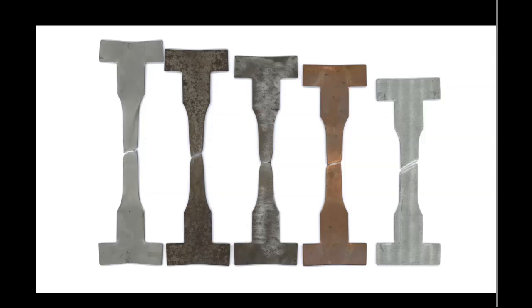So modulus of resilience, which statement describes it? A, the total energy absorbed by a material up to fracture. No, that's wrong, because at fracture both elastic and plastic deformation have already been at play. We don't want a material that has already been plastically deformed as a spring. Option B, the energy absorbed elastically per unit volume up to the yield point. This is the correct answer. And so far, I see this correct answer in most of the reports.